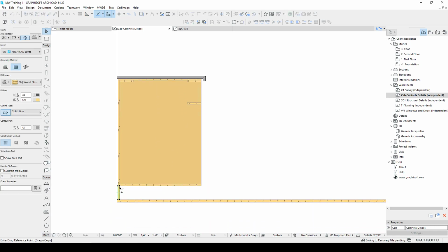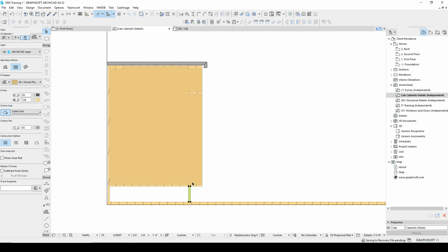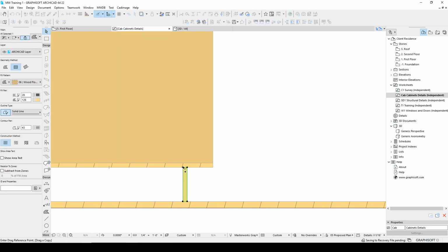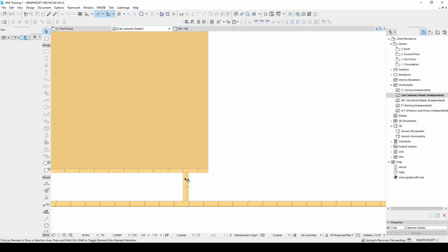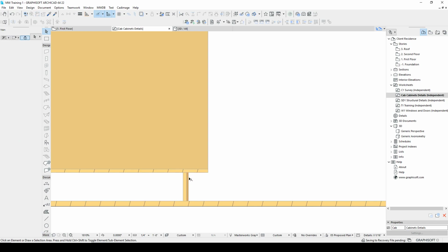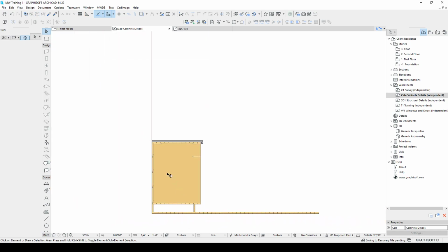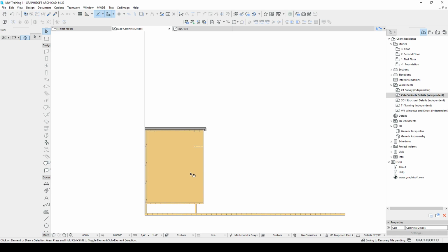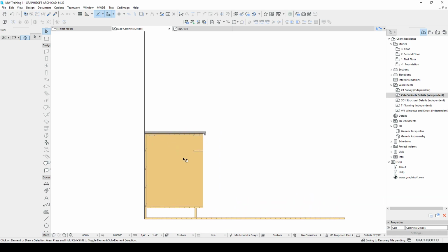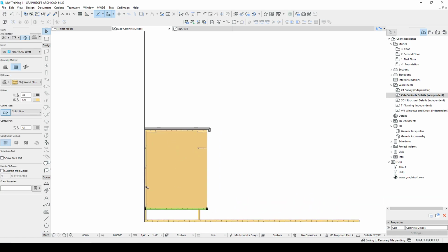Then I'm going to work on my toe kick. So move this here, come back 3 inches, which is a standard 3 back, 4 up. I may want to F9 this to copy and show my finished skin on here, which is usually 1/4 of an inch. I can change the color of this to represent more of a finished edge. And you can see that I'm just layering information. I can start drawing my backsplash. I can go on and on.